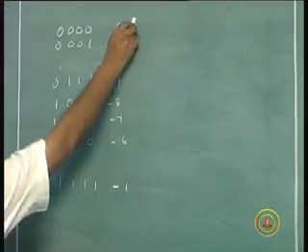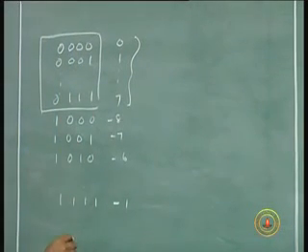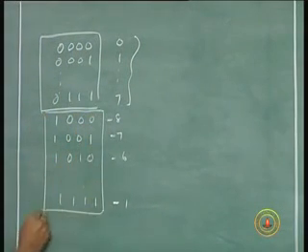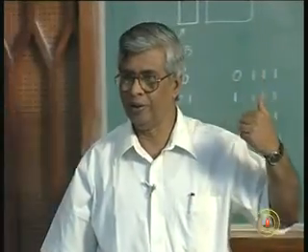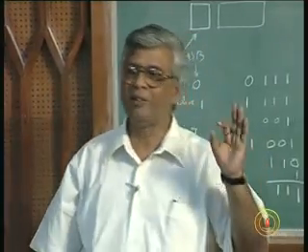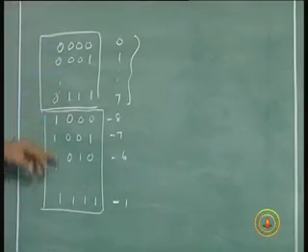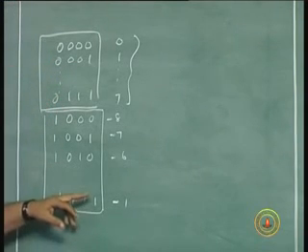So I have 0 to 7 and minus 8 to minus 1. The reason is I do not have to represent 0 two times. That is why I am getting one extra number for negative. I don't have plus 0 and a minus 0. I have only one 0. 0 is only once. So 0 is represented 0 0 0 0. So 1 1 1 1 is minus 1.